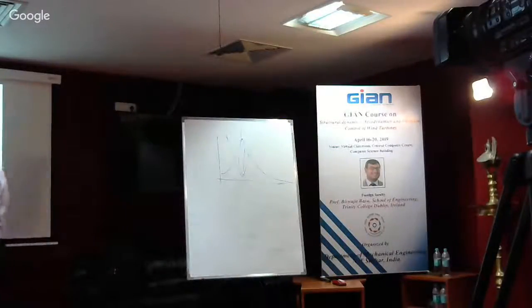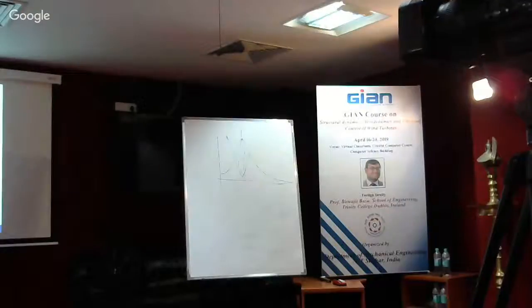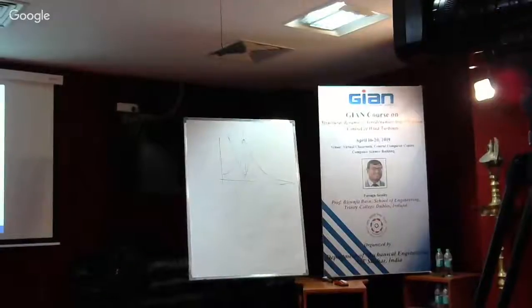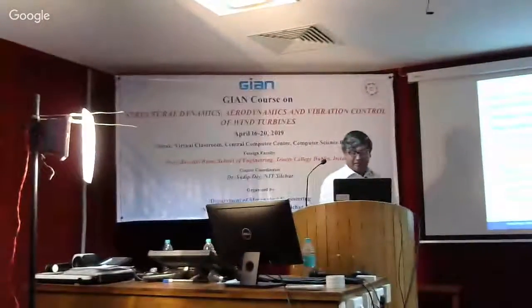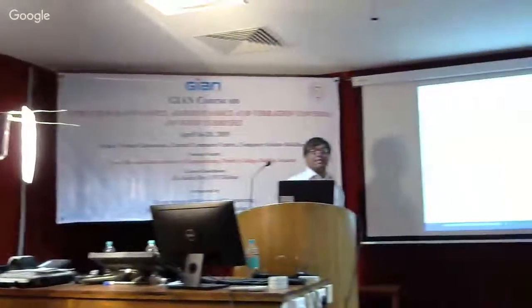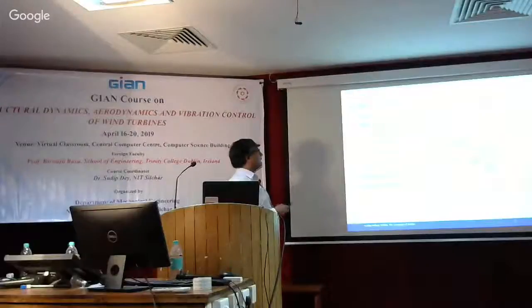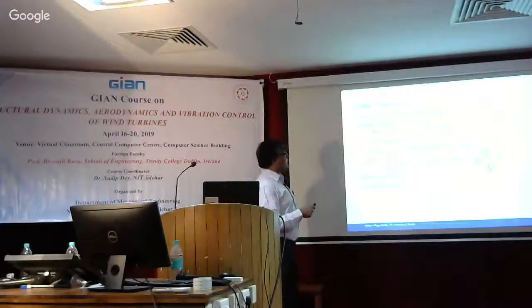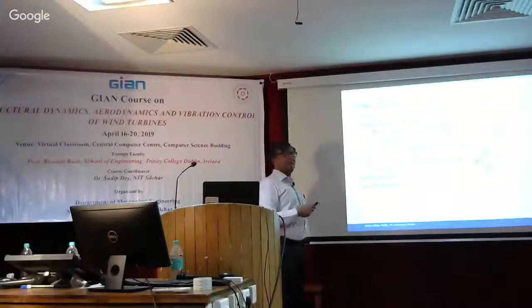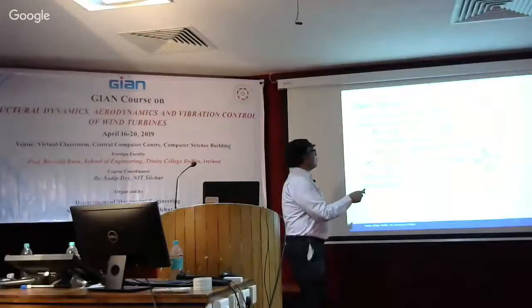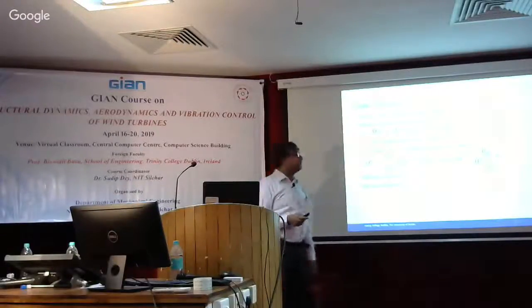Now, to understand this slightly more in detail or intuitively, we can look at the equations, and I'll show you how effectively it introduces damping. So let us look at the tower dynamics again. And let's say this is my equation of motion. And I'm measuring the nacelle acceleration, and obviously this is the velocity and displacement. So either this is the nacelle motion or tower motion, whatever you call it. And then your force is F, and this is mainly the aerodynamic force.